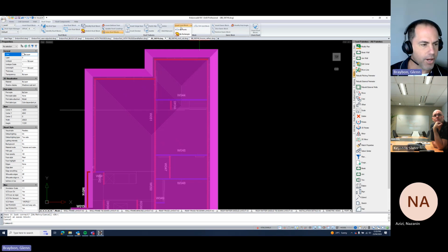Yeah, I totally agree. I think one thing I did use void blocks for as opposed to ceiling blocks was when you had a void block inside the truss envelope, not starting on the outside, on the ceiling line. If you wanted to put a unit up inside the truss that sat on top of the truss bottom cord. Okay, I didn't know you could do that.